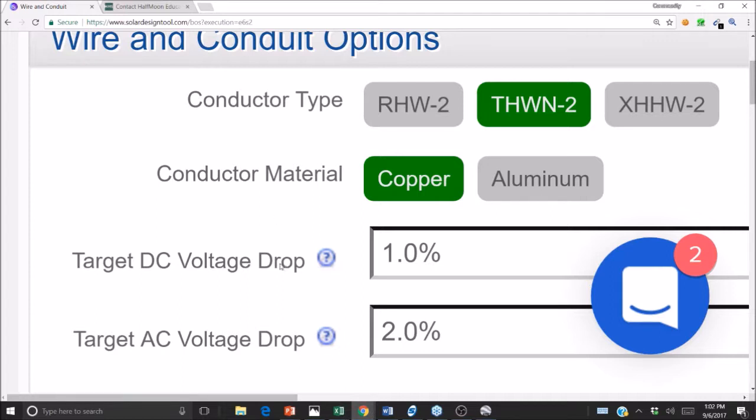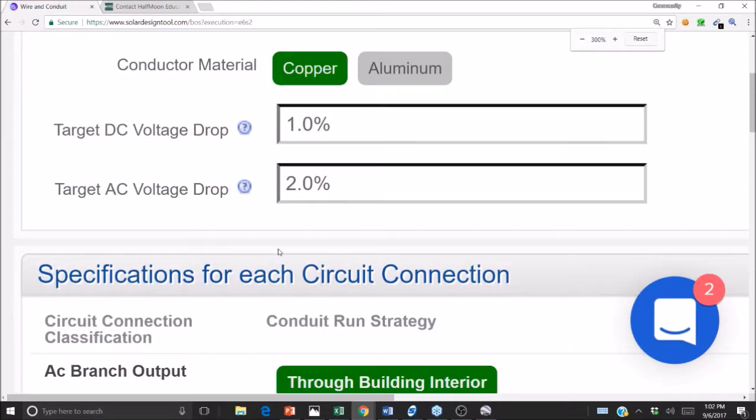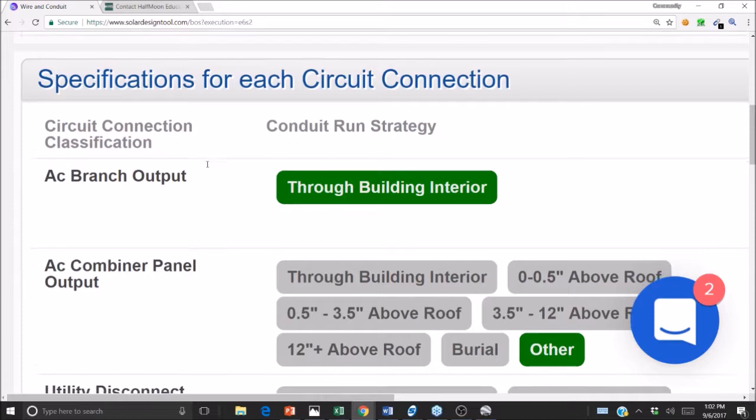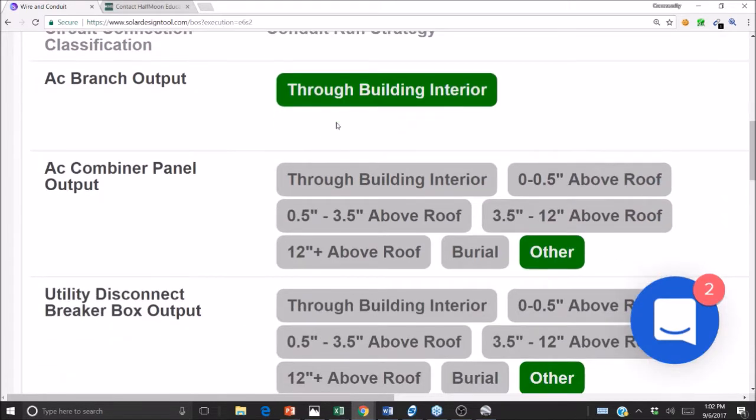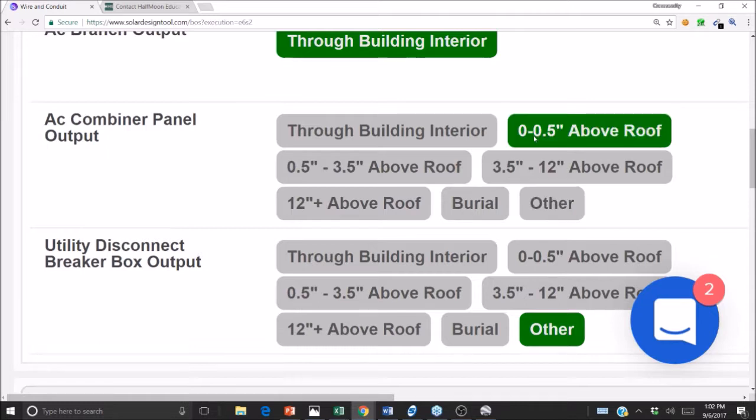We'll be covering those sections, coming through those sections, but it does make a useful guide. So anyway, then we get to our branch circuits and we see there's questions about, well, how close is the conductor to the rooftop? Well, there's different temperature derating requirements that have actually changed in NEC 2017.